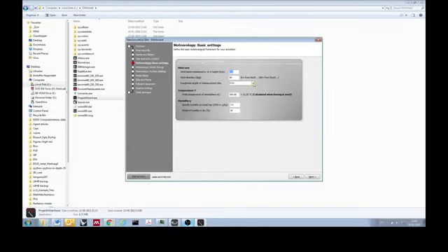In general terms, you can say that a very smooth roughness, a low number, is an area which has fewer buildings, like an open plain, or if you are situated on water, or where you don't have any obstructions. And 0.01 is considered an urban environment, and 0.1 is a very rough environment, like in downtown New York, where you have high buildings and these conditions here.